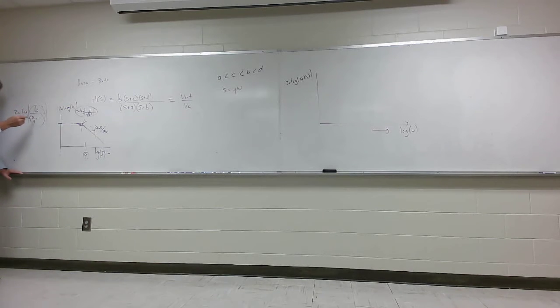So if we start at S over A equals 1, I would have the square root of 2 would be here, or it would really be here, wouldn't it, class? We assume at that point it starts breaking. Then if S over A is 10, we have 1 over 10. Well, the log of 10 is what? 1, times 20 would be a factor of minus 20 below. Do you all follow me on that, class? How many do? All right, so the 20 dB per decade would be for something like this.